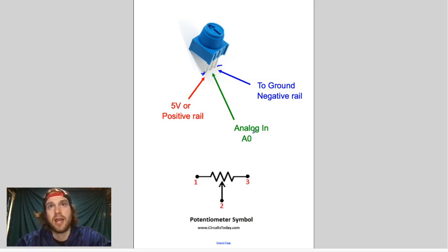And then your analog, this is going to go to port A0 on your Arduino, which is over on the weird side that we haven't used yet. So you have constant. So this one you will not hook up to a numbered port, which I think is one mistake. You never hook this one up to like port 13. I suppose you could, or port 10. You just hook it up to the 5-volt rail that's constant, and then we change the resistance by turning the knob. Okay, and I think I've said that enough.